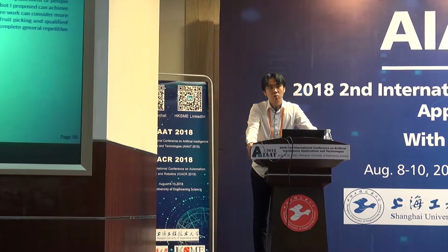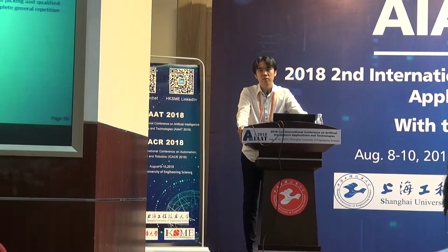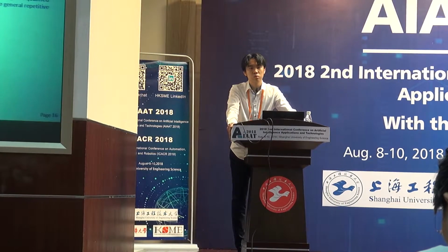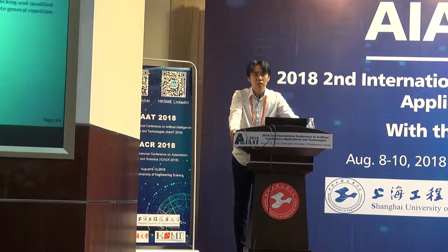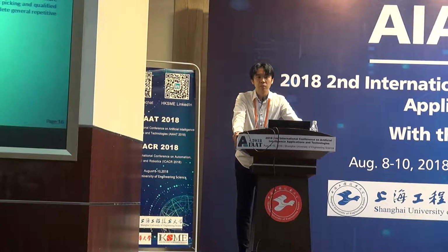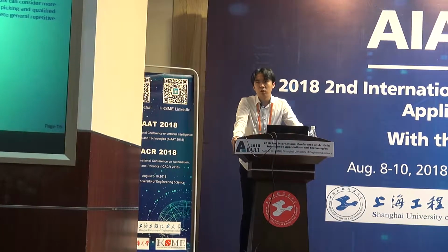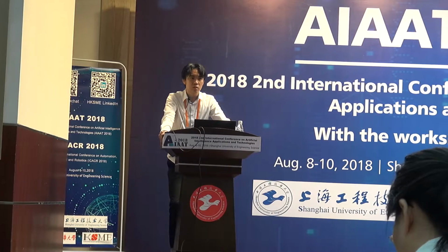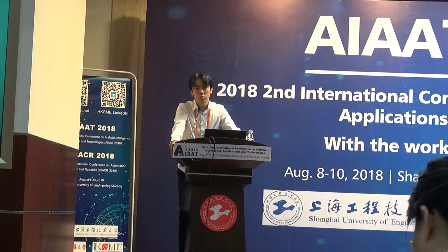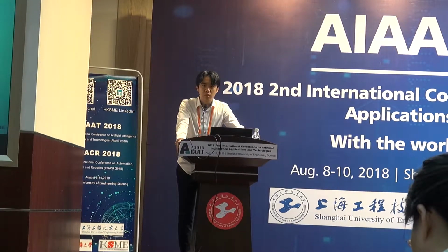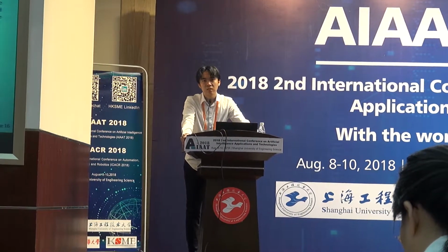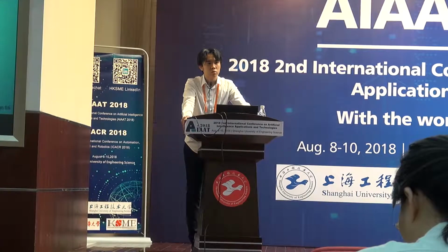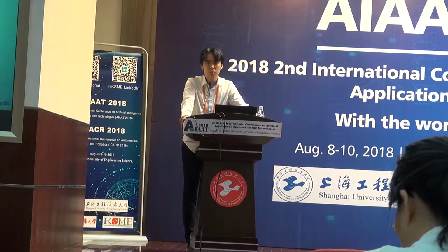First of all, my robot can only identify a sphere, which means a ball. If the object were a rectangle or an irregular shape, I would need to write some new algorithm to identify it, and I have not yet done any testing. Second of all, I can only identify the color as blue, red, and green, because I use RGB calculation. If the color is another color, for example purple, I don't know how to do it for now. And a problem I encountered in my testing is that if the surrounding light is very dim, I cannot successfully distinguish the color as blue or red. There is a 30% failure chance, which I'm still working on.